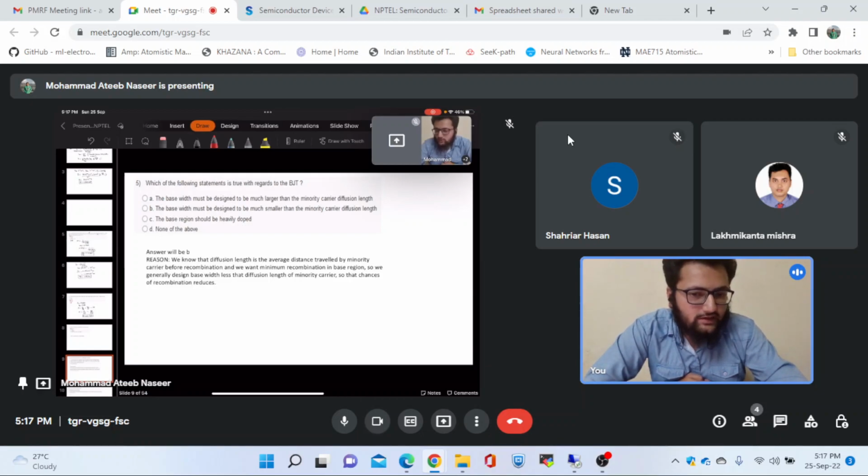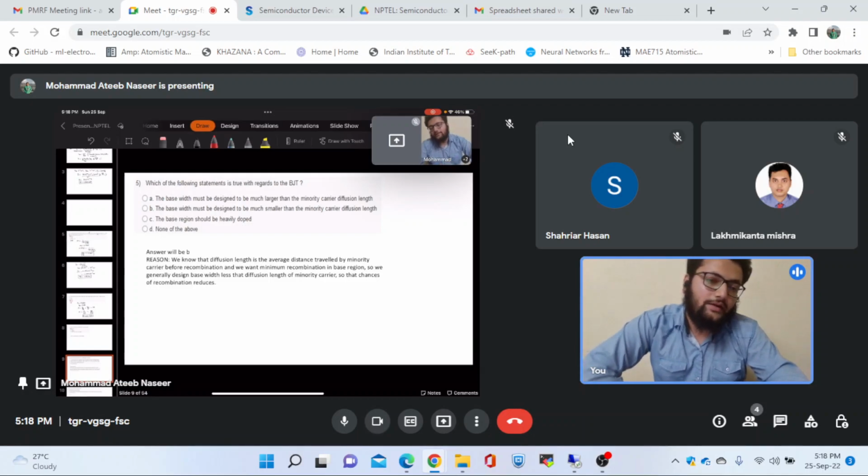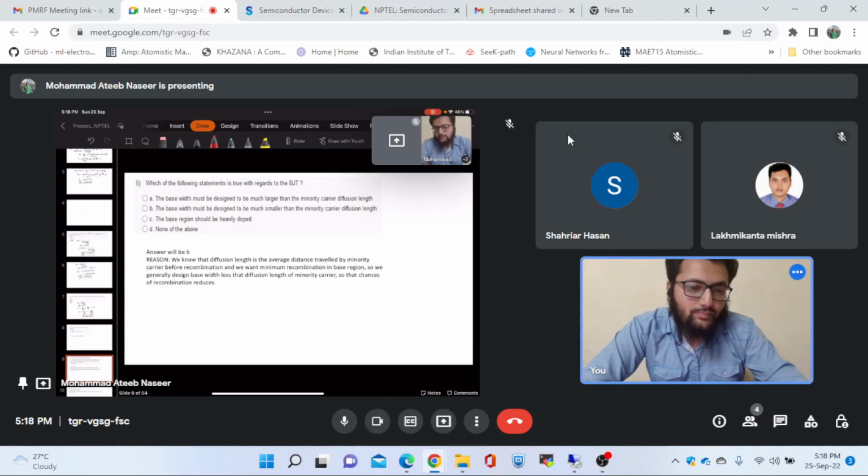Whenever we have some device, we generally say that if it is n-type it has good mobility. This is a general misconception. It is valid for devices like silicon, because the mobility of holes is much less than the mobility of electrons, and in that case we always see that NFETs are faster devices. But that is not the case with every material.